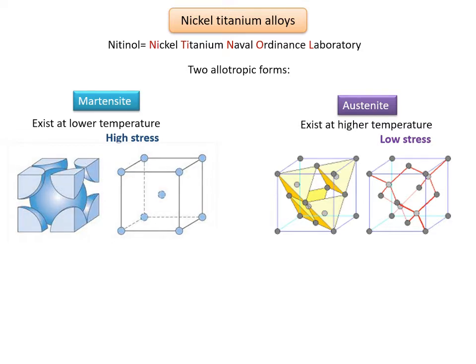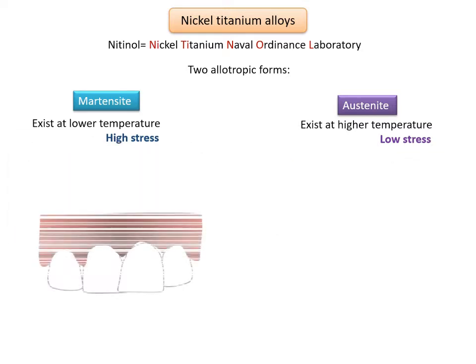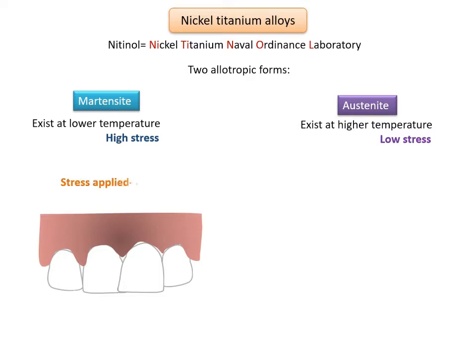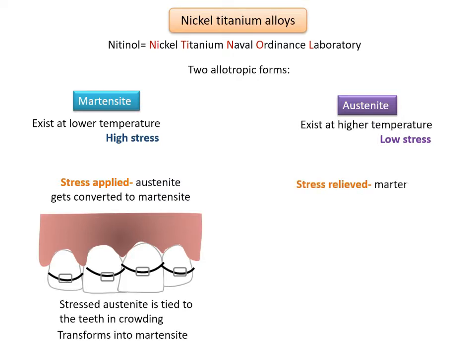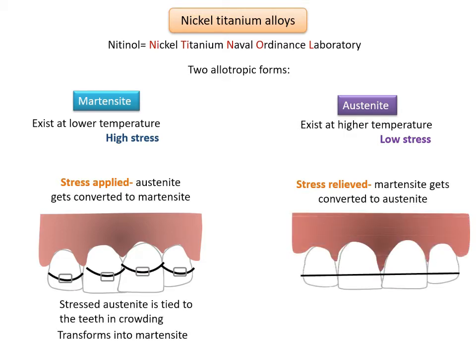The shape memory characteristics of nickel titanium alloys are associated with a reversible transformation between the austenitic and martensitic phases. The martensitic phase forms from the austenitic phase over a certain transformation temperature range or when the stress is increased above some appropriate levels. The difference in the temperature ranges for the forward transformation from the martensitic phase to the austenitic phase and for the reverse transformation is termed hysteresis.